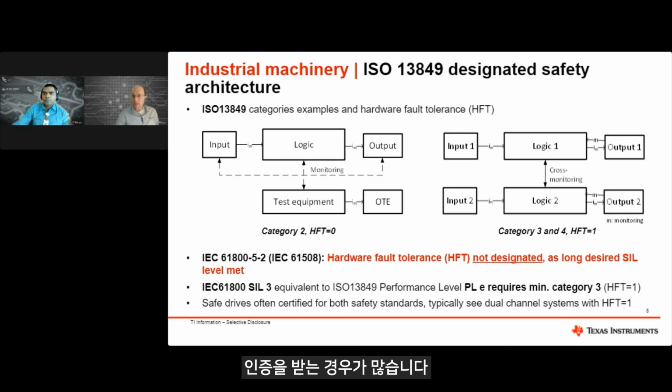A typical safety function implementation consists of three steps: sensing, processing, and actuation. In some cases, an additional function of communication with an external component is required. For the safety of sensing, C2000 MCUs support redundant and diverse sensing peripherals, such as the ADC and the comparator subsystem, CMPSS. Built-in hardware sensor data processing and automatic result comparison in hardware is implemented for the microcontroller. This saves significant overhead of processing the same data in software, and it saves software development time as well. Extensive interconnection between the sensors and actuators via the on-chip crossbar architecture can activate the safe state even independent of the CPU.